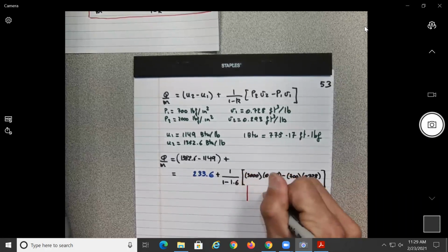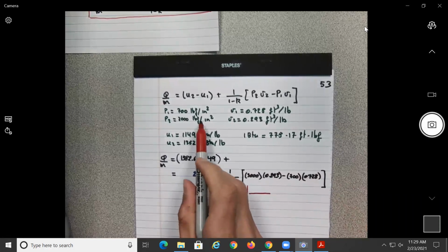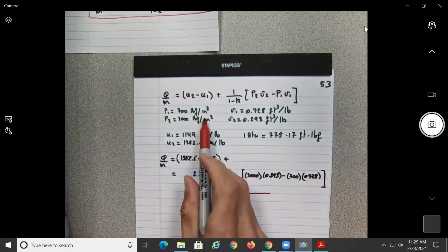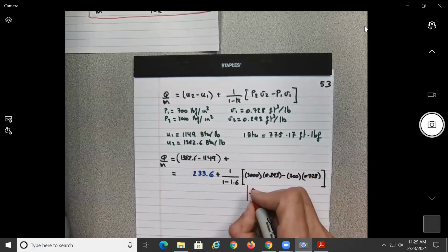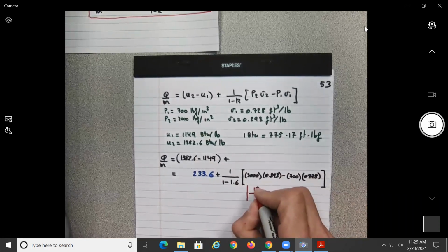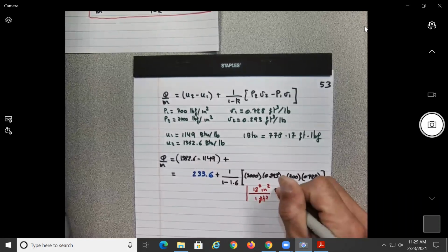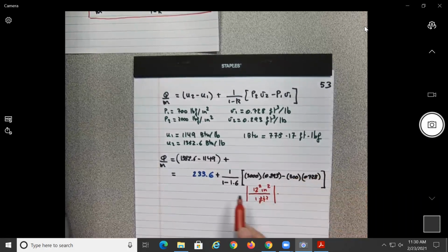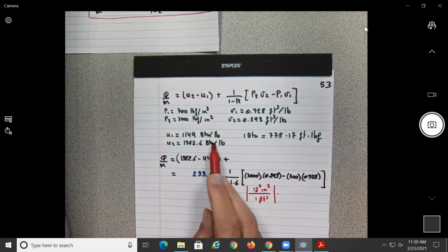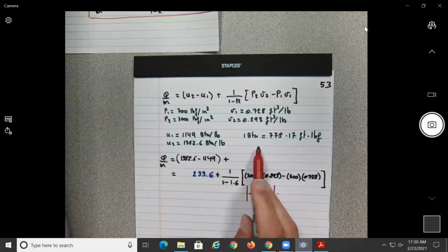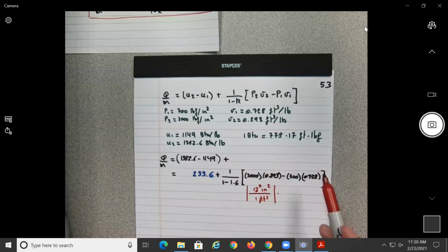First thing we need to do is to transform what? Those inch square over here for the pressure into square foot, no? Okay, so this is divided. So what do we have? We're gonna have 12 inch square equal to 1 foot square. I know it's 144, you probably know that. And then what were the units for the internal energy? BTUs per pound, no? So we need now to transform all this one here, the foot LBF, into BTUs.